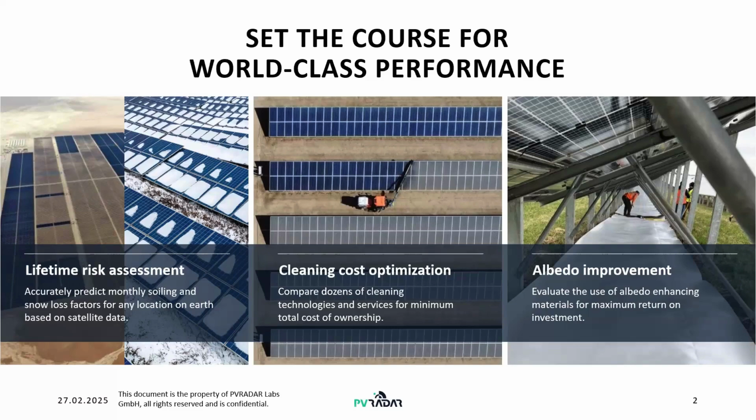In the early design of a project, there are always some assumptions being made. For example, developers generally put something like 2% in soiling losses, 2% in temperature or snow losses. From our point of view, that's a critical point that needs to be improved.